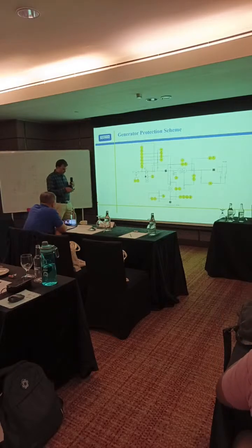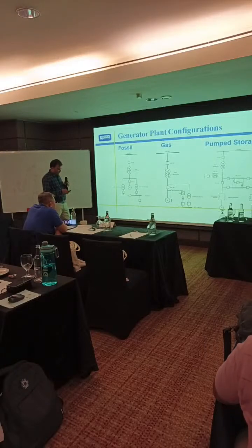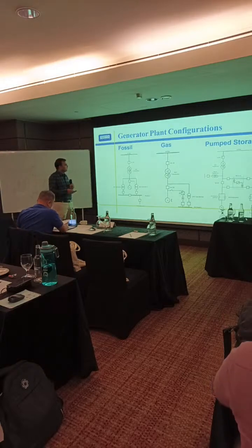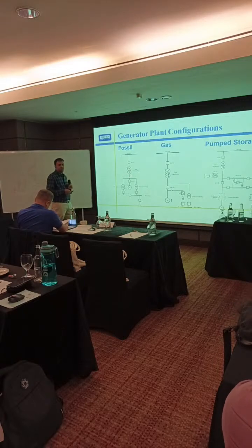If it is an individual protection, then it is easy, as we are doing the differential protection, that will be applicable to all. This is the same transformer that we tested earlier, so the protection will also be the same, not different.